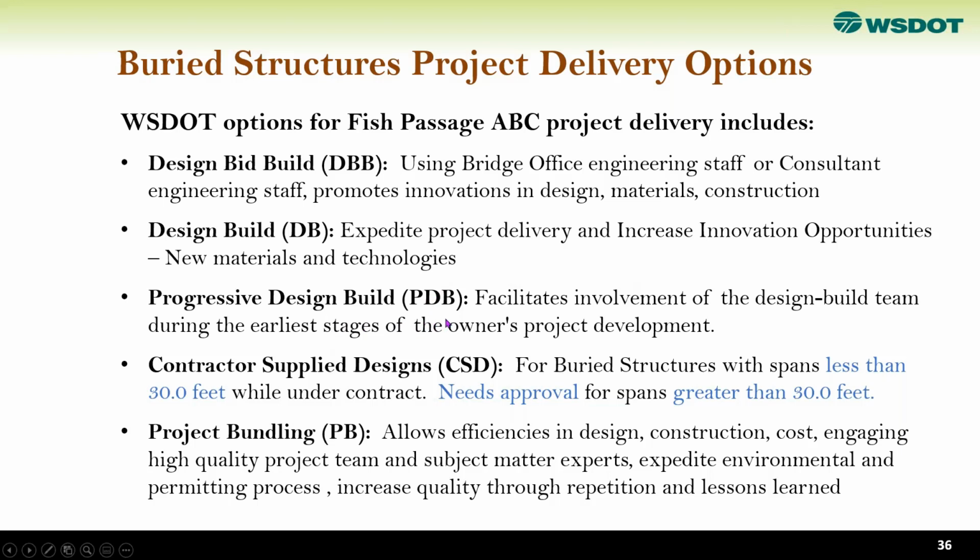Progressive design-build is a new process used by WSDOT to facilitate the involvement of the design-build team during the earliest stage of the owner's project development. And then contractor-supplied design is used in some cases successfully. This is for buried structures with a span less than 30 feet. We do allow that under contract, but also for a span over 30 feet, on a case-by-case basis based on approval, we can use contractor-supplied design.